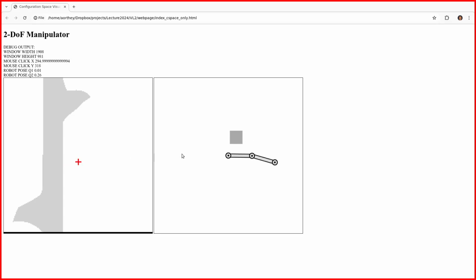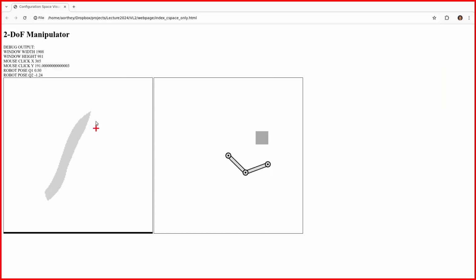And so this configuration space is, of course, dependent on the position of the obstacle or of the objects here. For example, if I move this object a little bit to the right, then the configuration space also transforms. If I move around in this configuration space and come into this gray area, then I'm in collision here, but you can see that this area is much smaller, and I would say planning when the obstacle is a bit farther away is of course a bit easier to do.